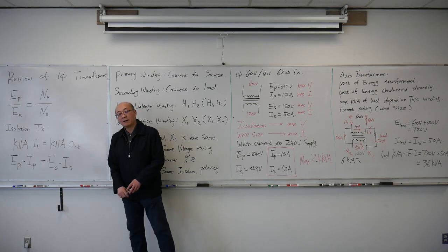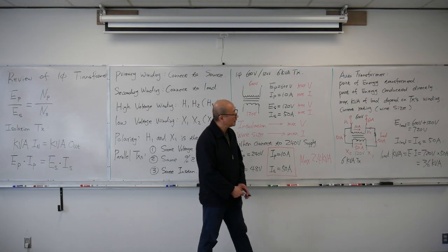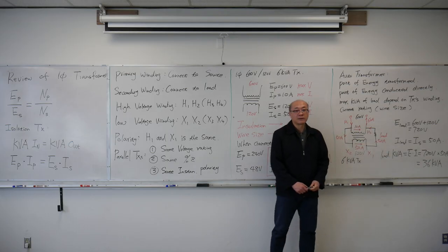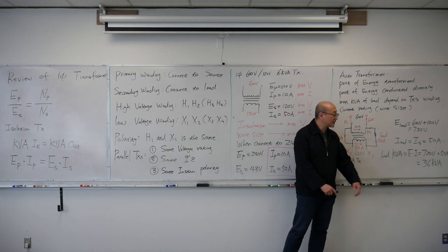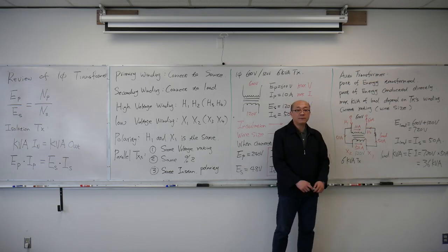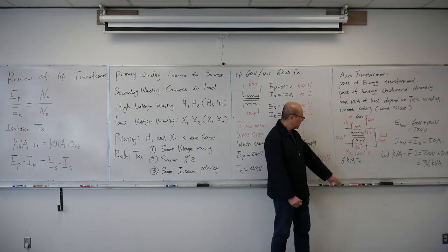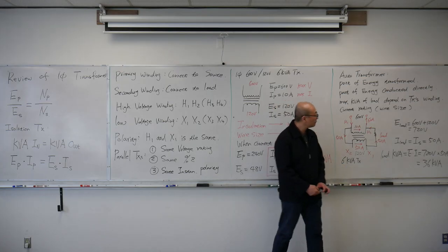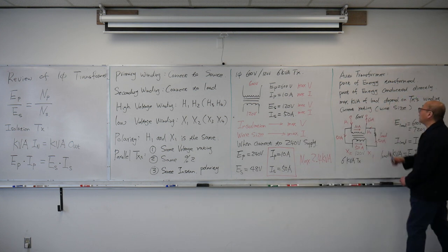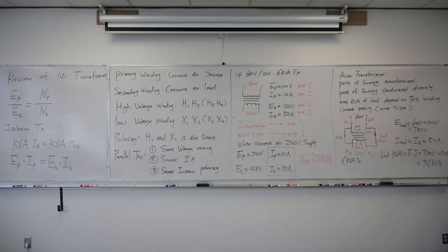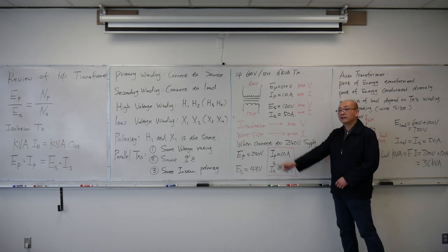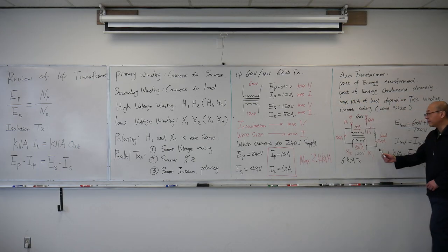We're not going to limit it by the kVA rating of the transformer, but if we calculate here 600 volts times 60 amps, we will still have the load draw 36 kVA. The input will also be 36 kVA. We just cannot use the transformer kVA to do the calculation for the load. So the maximum kVA of the load depends on the transformer winding's current rating, because this transformer winding is rated at 50 amps. In this configuration, my load can receive 50 amps.